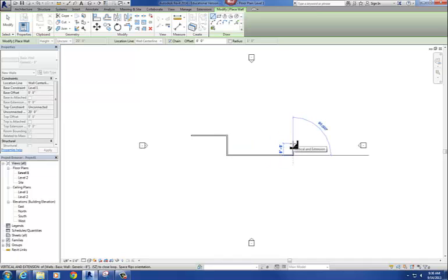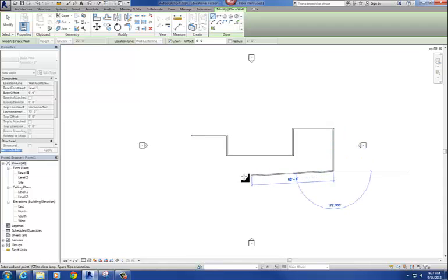Now the default dimensions for Revit are feet. So if I wanted to just type in feet, I can just go 20, enter, and I don't even have to hit the foot button. If I want say 30 foot 5 inches, I can type 30 space 5 without putting any feet or inches in there, and it'll give me 30 foot 5 inches. So it's like a shortcut basically. If you just put a space between them, it understands that the first number is feet and the second number is inches. So those are the basics on actually drawing the walls.